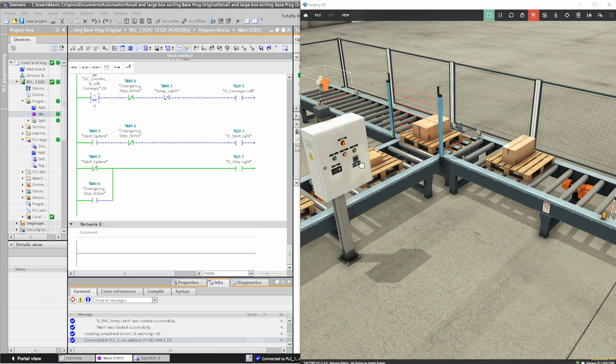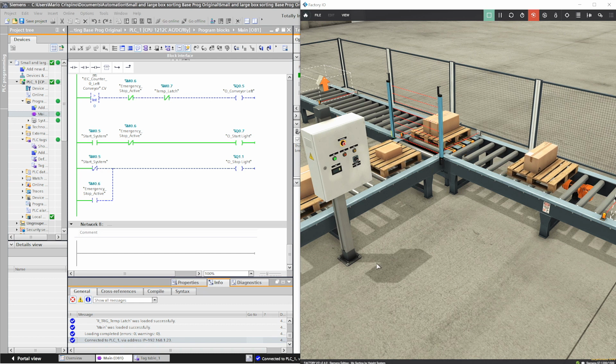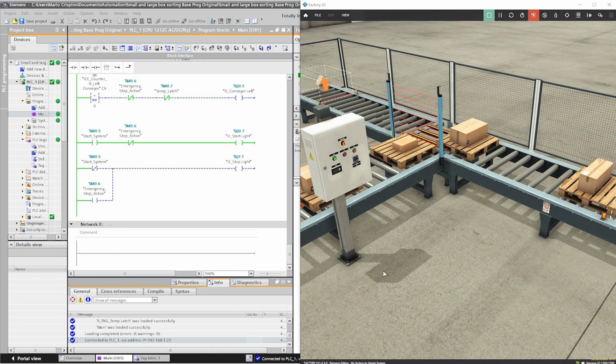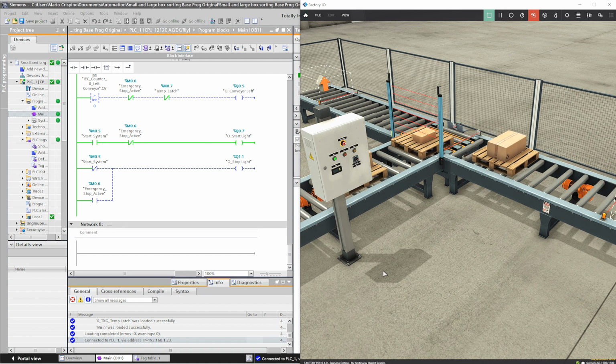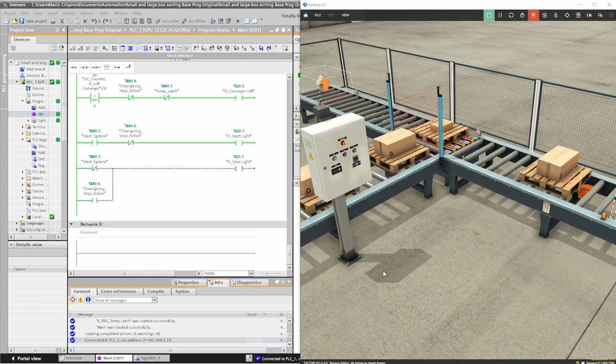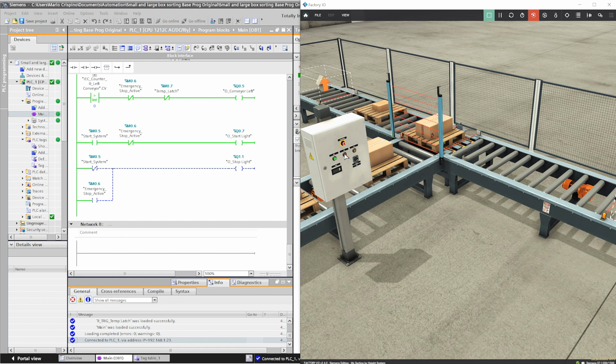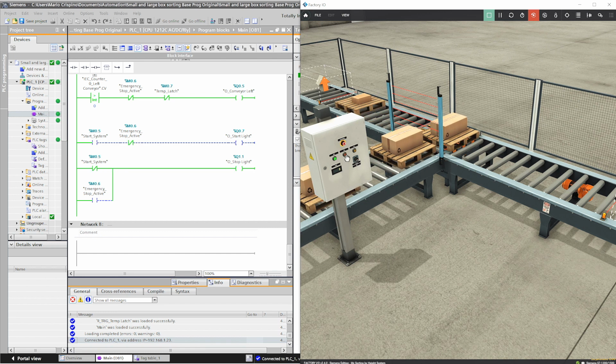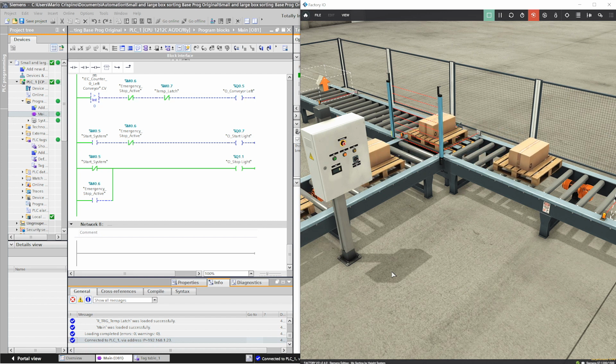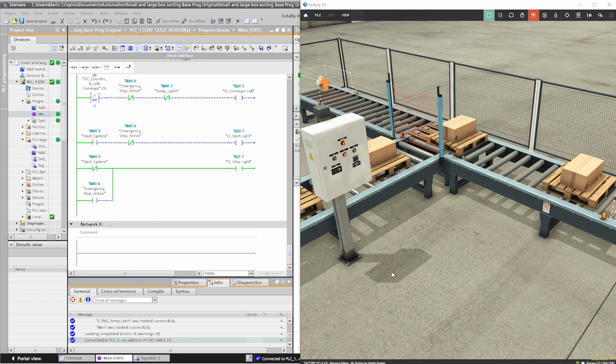Then press the start button again. Now let's press the stop button just as a pallet is detected by the beam sensor. The pallet is then loaded when the small loader conveyor is not busy, and the entry conveyor stops while the remaining pallets are transferred.